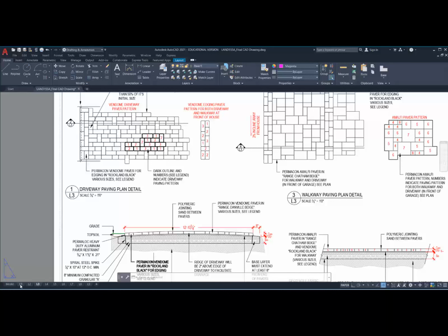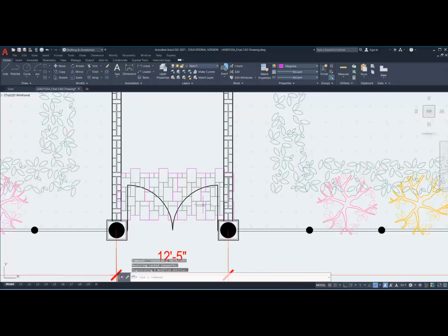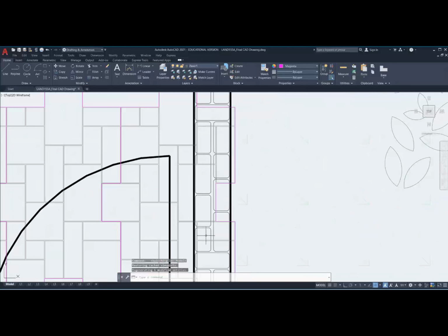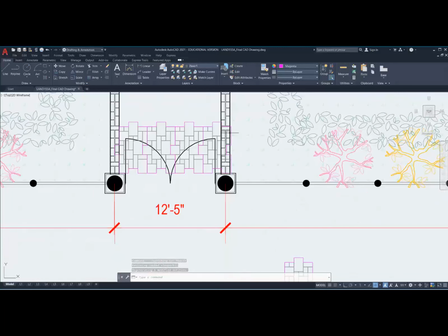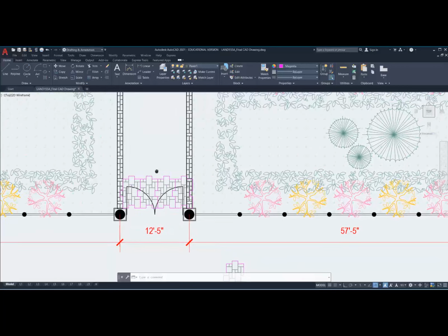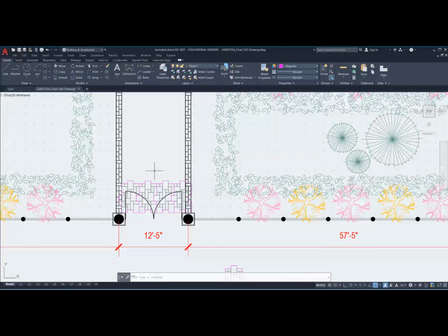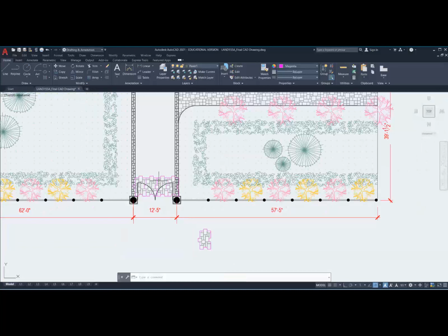Because if I'm cutting, and let me go back to the model, if I'm cutting out these tiles here, well, what I'm actually doing is cutting them right along their seams or right in the midpoint, so then I can continue on to the next tile or to the next placement of that tile and have a very efficient installation with minimum waste and great cuts. And that's what you'd like to be able to do within your project. So consider this when you're working on your particular project.